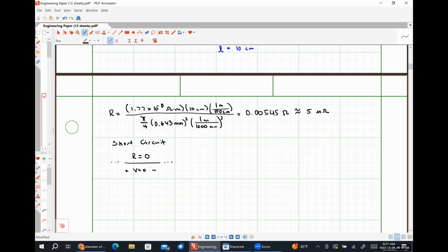On the flip side of that, we have an open circuit, which looks like a lack of wire, for lack of a better term, or just a set of open circuited terminals, right? So there's no conducting path. The resistance of an open circuit is infinitely large. This isn't particularly true, just like the resistance of a short circuit isn't particularly true either, right? If I apply a large enough voltage across nothing, I will cause dielectric breakdown to happen and electricity will flow. It will be dangerous.